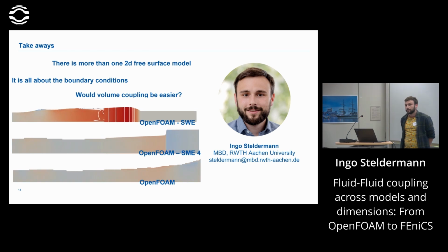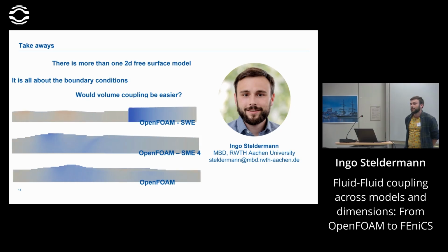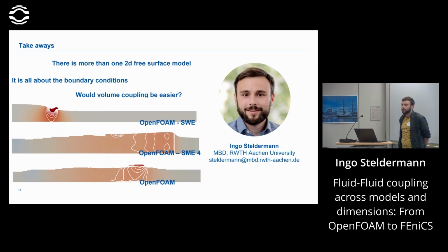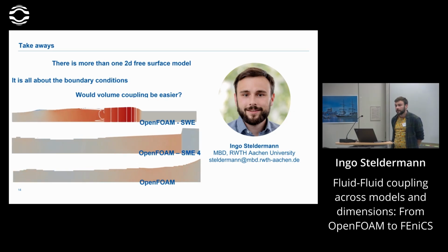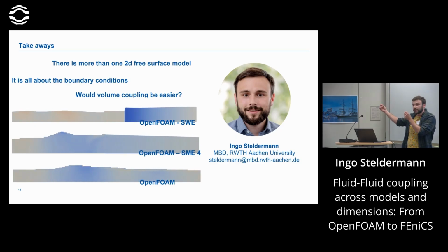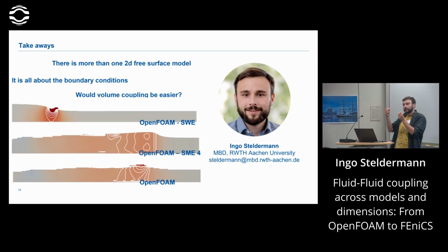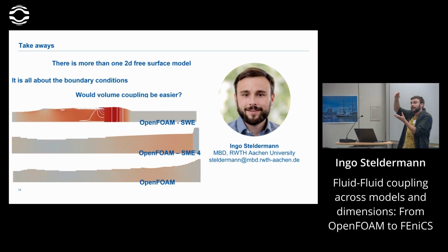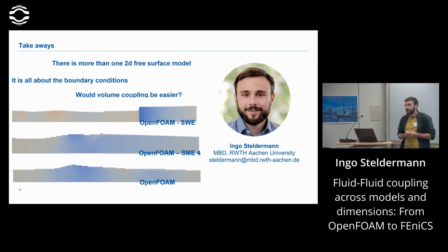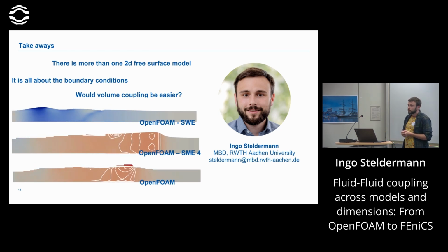But again, on the full 3D model you have the profile. So yes, it is true at the interface. What happens downstream is now an approximation. But it is true at the interface. I fully agree, and this is where this also comes from. In our formulation we don't use the shape factor, deliberately, because we want to dynamically construct the profile from the shallow water side. We want to get rid of the shape factor and instead have models that can tell you what the actual profile looks like, coming from the reduced-order side. Okay, thank you. More questions?